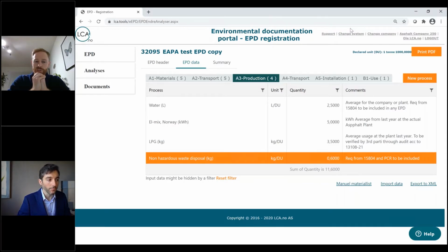And data can be added, publicly available EPDs can be added directly, or any document that contains EPD indicators. And also if a supplier is able to calculate values according to the EN 15804 standard, it's possible to implement that. This can be done by companies themselves or from consultants that help them to calculate the values with other tools. Brilliant. Okay. Thank you. Just carry on then. Thank you.